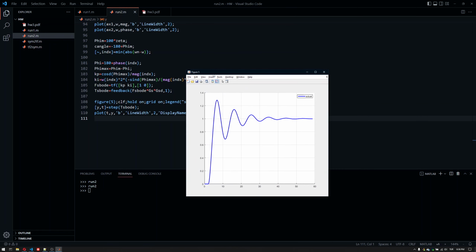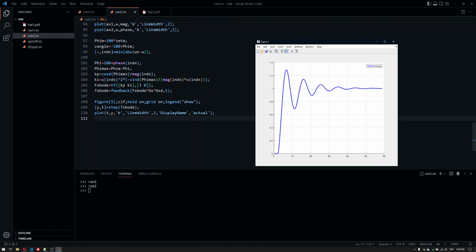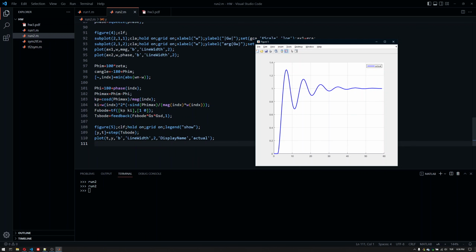Now, there are many papers on PI or PID controller design using Bode. This is kind of a phase lead controller algorithm. You look for a certain phase margin, and then you look for the natural frequency that you're interested in, which is omega n, directly omega n in this case. And then we have the phi max approach, which we had in the phase lead controller 2, as far as I remember, where we calculate beta.